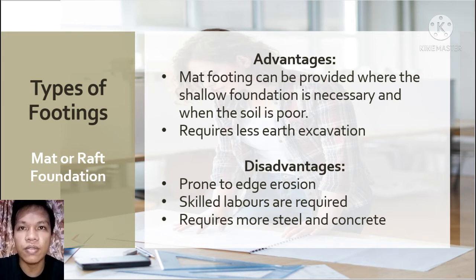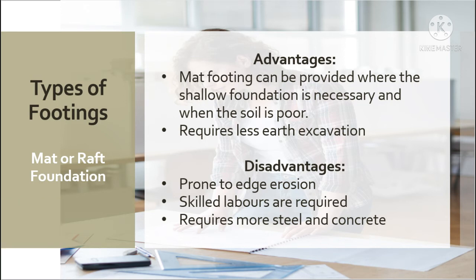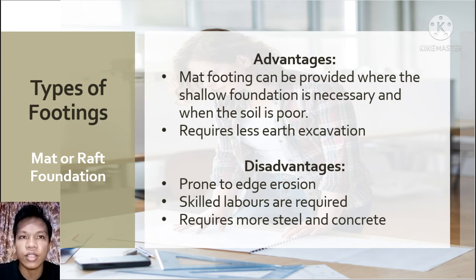Disadvantages: raft foundation is prone to corrosion. Skilled labor is required as compared to other foundations. It requires a lot of steel and concrete and hence it will be expensive.